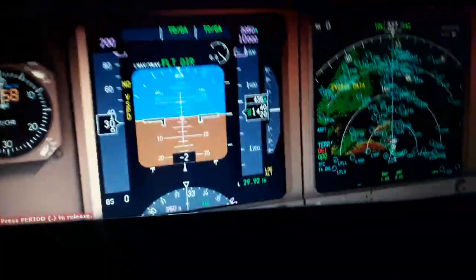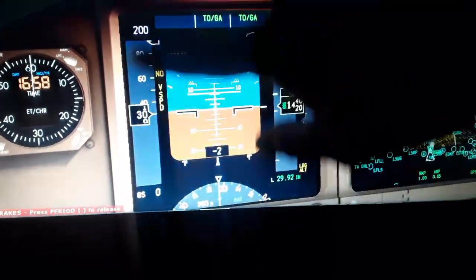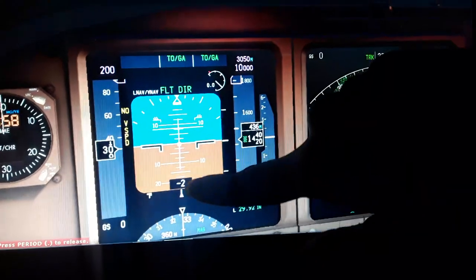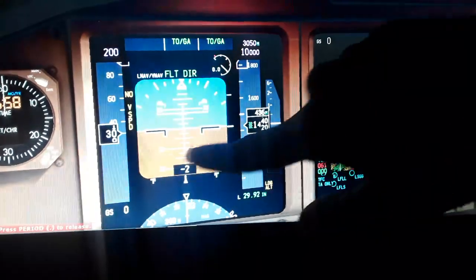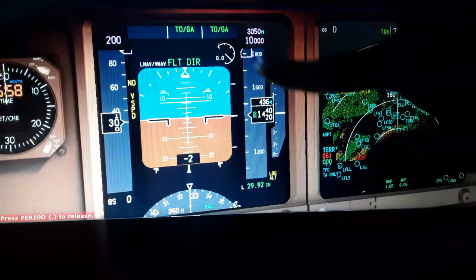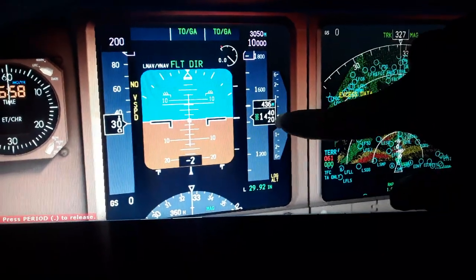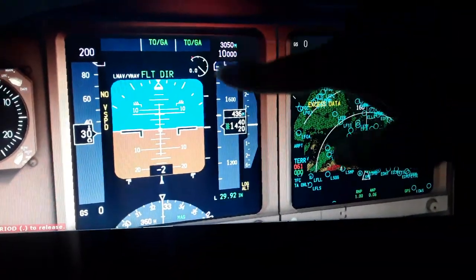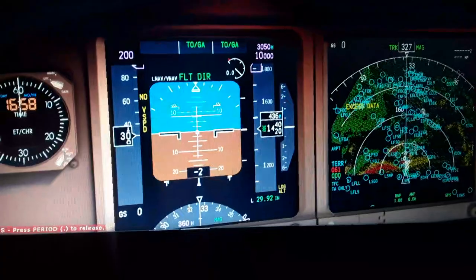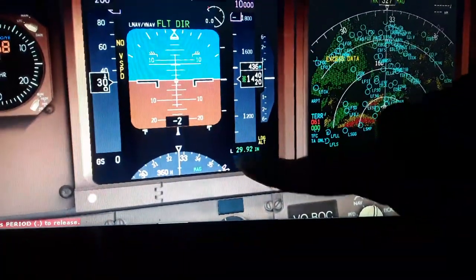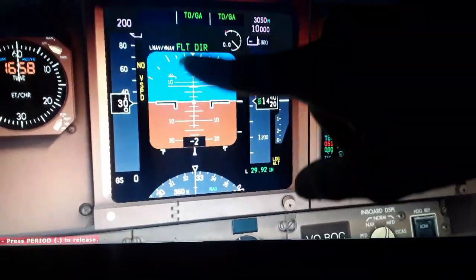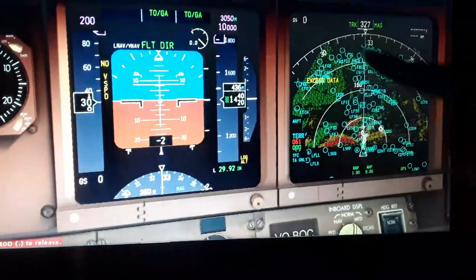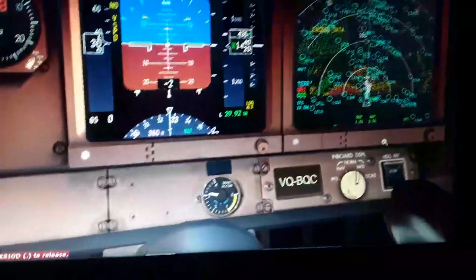So we have the airspeed indicated, the ground speed, and the airspeed selected from the autopilot director system panel displayed in purple. You can see here the altitude indicator, the barometric pressure altitude 1,430 feet or 436 meters. The altitude selected from the autopilot director system panel and the barometric pressure of the outside atmosphere, 29.92. The radio altitude 2 feet and the magnetic heading.